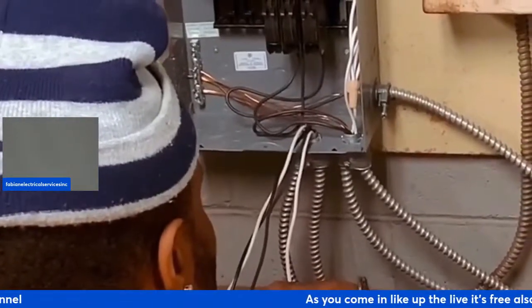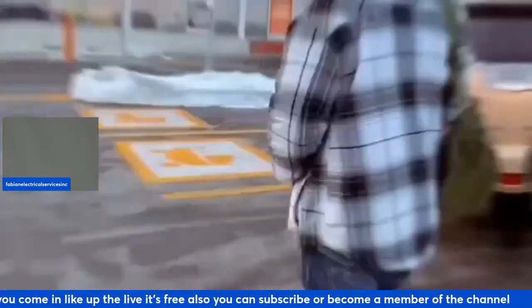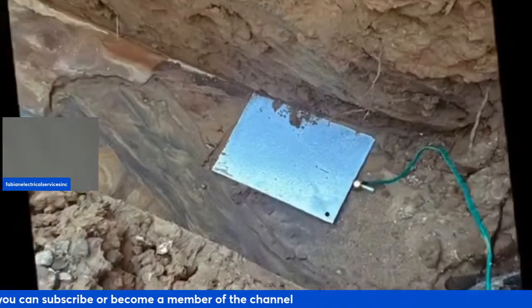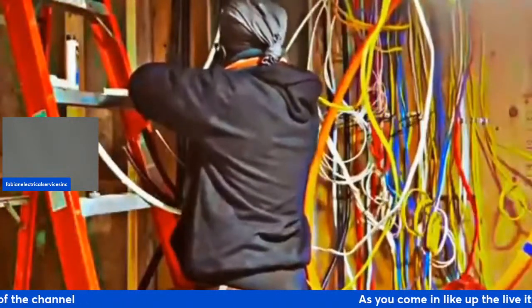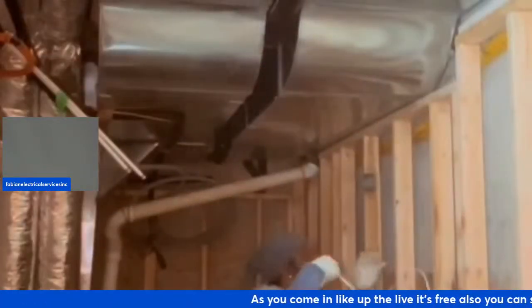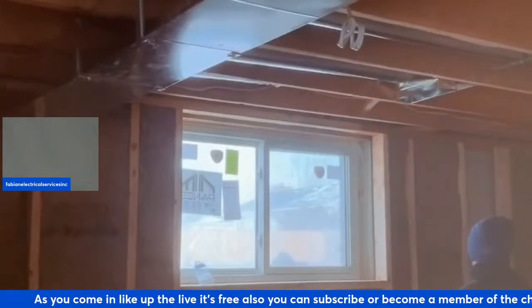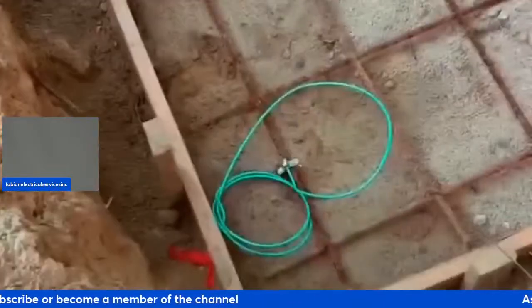Surges can be caused by lightning, high power appliances cycling on and off, or problems with your home wiring. Key features to look for is the joule rating. This indicates the amount of energy the surge protector can absorb before it fails. A higher rating offers more protection. Indicator lights: some surge protectors have lights to confirm they are functioning correctly and protecting your devices. And data line protection: some models offer additional protection for data lines such as coaxial and Ethernet cable.